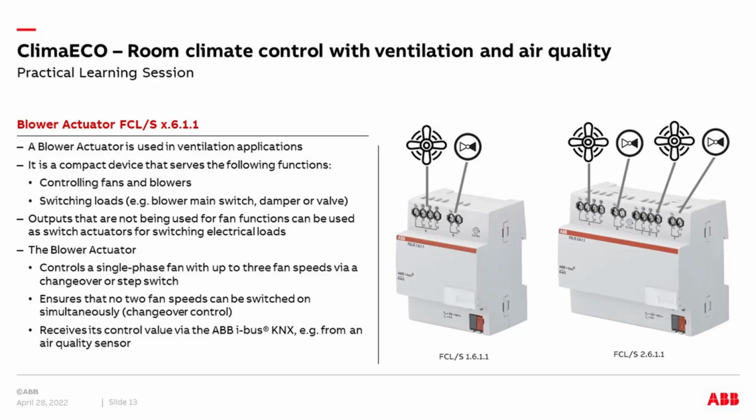In principle, a component with relays inside, controlling fans and blowers, but also a fourth relay to turn on any other load. Could be also light, but in terms of air quality control, it could be a main switch of the fan, it could be also a damper or a valve, whatever, and can be integrated. We have components with 1 output or 1 channel, or with 2 channels. And it's possible in the 2-channel component, for example, to use unused fan relays for individual relay control of any other loads. Also light control could be possible.